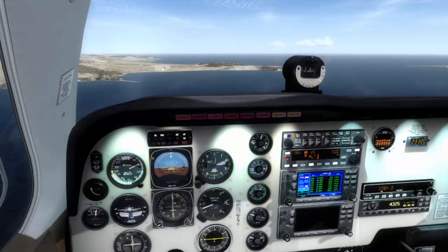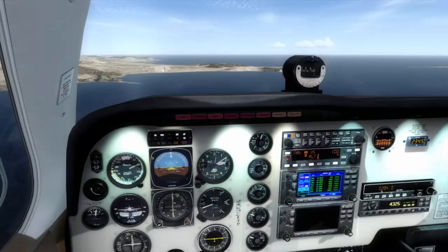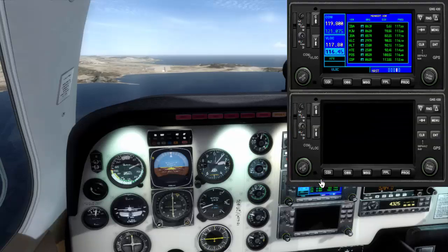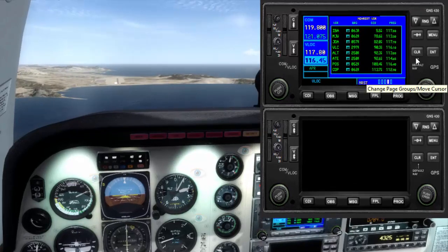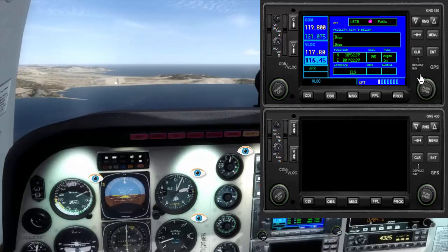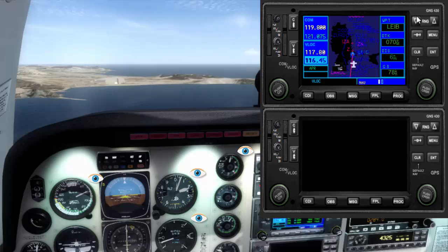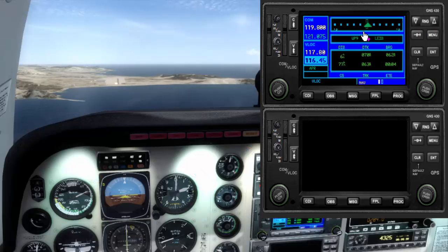And if you remember in the chart, on the left side, we have the minimums, and the minimums are established at 810 feet, or 800 feet, I don't remember well, but anyway, it is in the chart. And when we are exactly at a distance from the IBIZA VOR of 2 nautical miles, at that point we will have reached the MAP, the missed approach point.